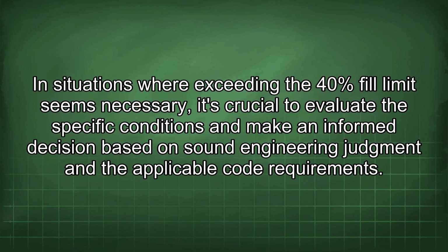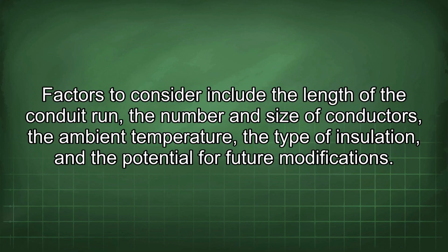In situations where exceeding the 40% fill limit seems necessary, it's crucial to evaluate the specific conditions and make an informed decision based on sound engineering judgment and the applicable code requirements. Factors to consider include the length of the conduit run, the number and size of conductors, the ambient temperature, the type of insulation, and the potential for future modifications.